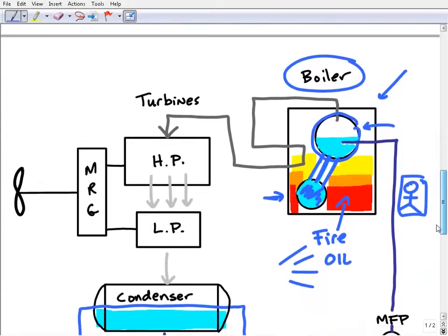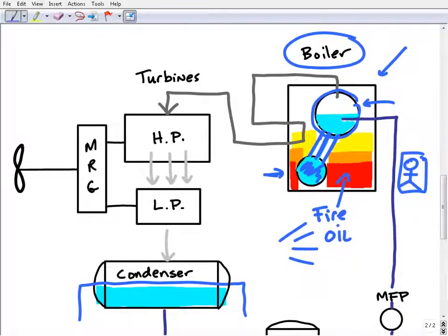All right, so here's our boiler. It's our heat source, right? We're spraying in some sort of marine diesel fuel. We're atomizing it, kind of like spraying it like a spray can, and it's burning just nice and toasty here. We have our water, and now these tubes right here are getting hot, obviously, and it's creating steam. Our steam is bubbling up through these tubes, and eventually it's going to escape up here in our steam drum.